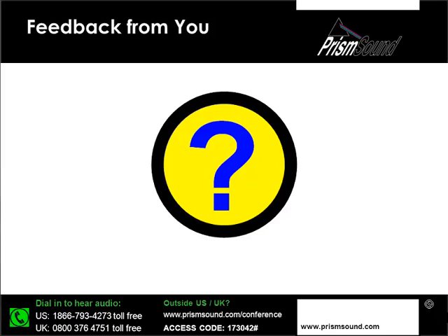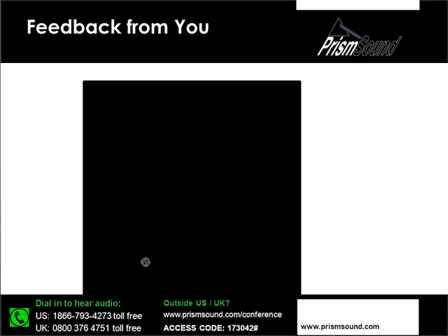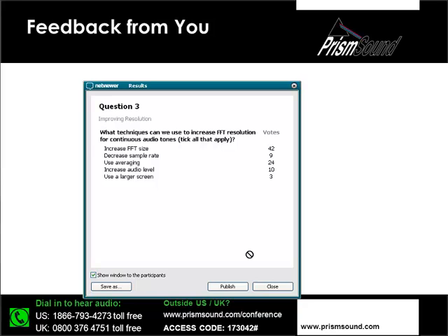Okay, let's bring that survey to a close and take a look at how you have responded. What I can confirm is that all 3 of the top 3 options in this list are potentially valid ways of enhancing the resolution of our FFT. A good majority of you correctly identified that increasing the FFT size will help. Decreasing the sample rate may be counterintuitive, but that does also increase our FFT resolution. Averaging, again, can help our resolution.